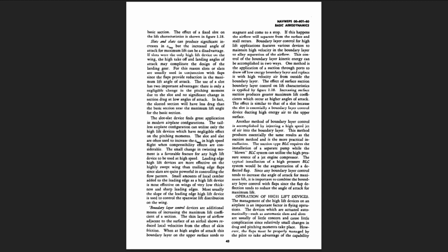Since any boundary layer control tends to increase the angle of attack for maximum lift, it is important to combine the boundary layer control with flaps, since the flap deflection tends to reduce the angle of attack for maximum lift.